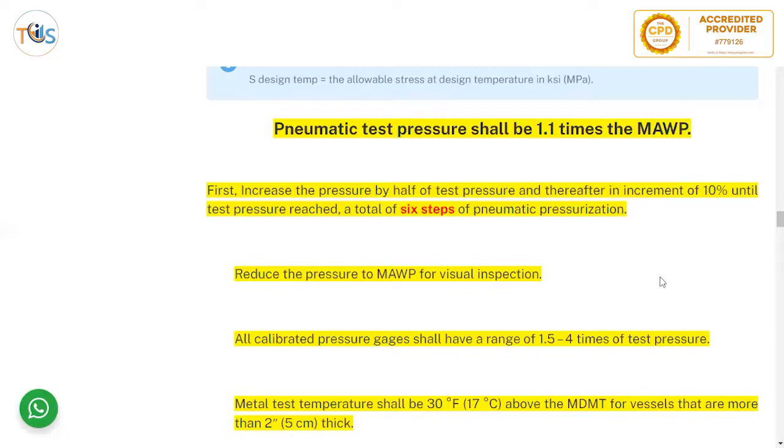and a pneumatic test is a very dangerous test because the gases need to be compressed, and it's also much more time consuming because it takes a lot of time until the gas is compressed and the pressure is built up. It takes hours. Plus, if there is any leak, failure or explosion, it works like a time bomb because you're compressing and storing a lot of energy in the gas. Once the gas is released, it just bursts, whereas for water the damage is not so much.